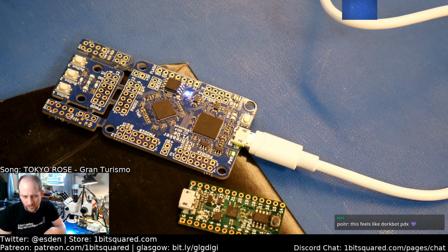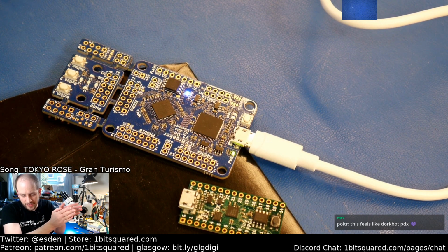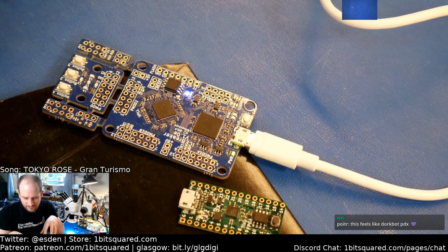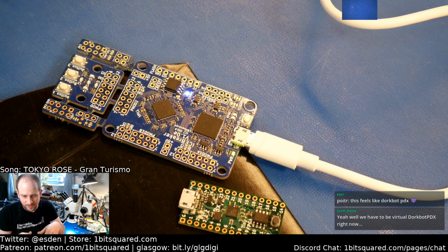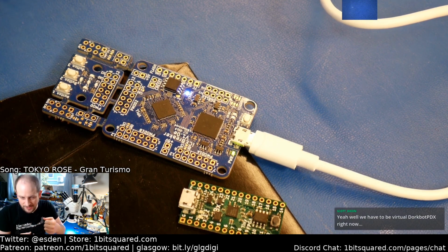Just like on a microcontroller where you would have a bootloader, you can have a bootloader at the beginning of the flash and right after that the application. And the bootloader can either run itself to flash a new payload or jump to the payload. Similar functionality you can do in an FPGA where you have two bit streams. The bootloader starts, sees that there is a valid bit stream, or it is being stopped by the computer to flash a new bit stream, and then jumps to that, reloads that.